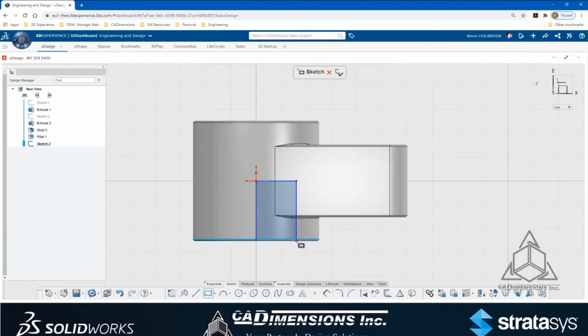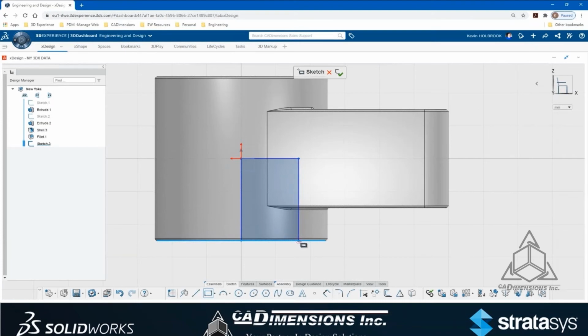And, you know, sometimes you may want to pick up an edge to associate it. Other times you may just want to extend it down and add the relationship depending on what you're trying to do. In this case, I just wanted to show that you can still pick up silhouette edges and you can apply those relationships. It's very easy to remove relationships. Select the geometry align, we get our pop-ups for the relations, and you can just click delete on the keyboard as you'd expect.